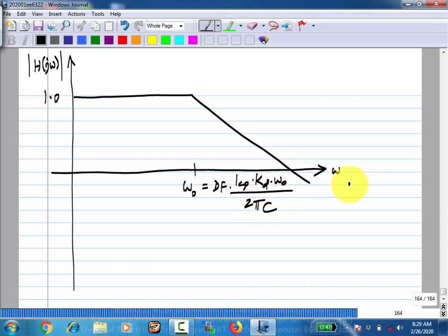Okay. So this 2 pi here comes from the phase detector gain. Because the denominator has 2 pi, don't assume that this is the cyclic frequency. This is the radian frequency, and if you want the cyclic frequency, you have to further divide that by 2 pi. Okay.